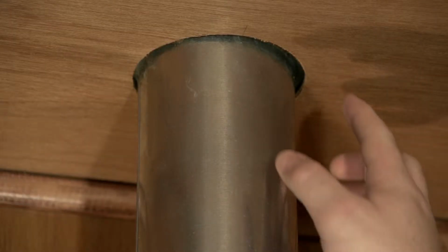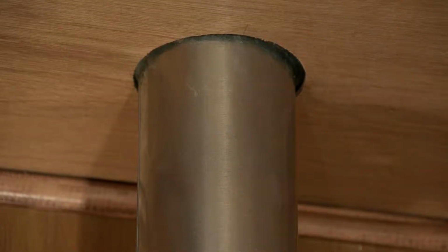Another common penetration are our vent stacks, perhaps from an appliance such as a dryer or a hot water heater, and they're not sealed correctly around the top, so there's a lot of air leakage here. Another common area is our attic access. These are very rarely weather stripped or sealed properly, and they can be a very high source of leakage.